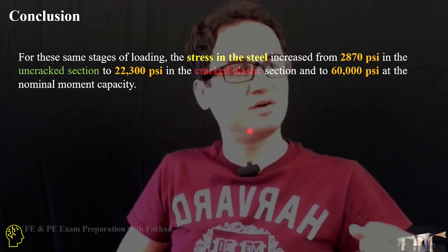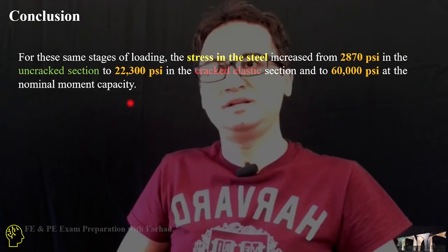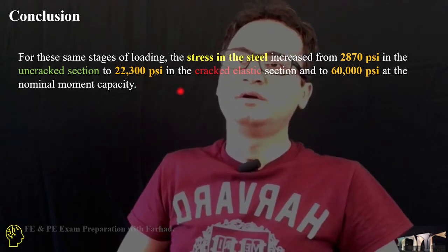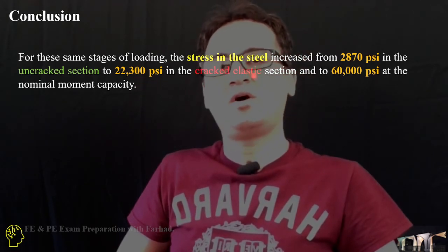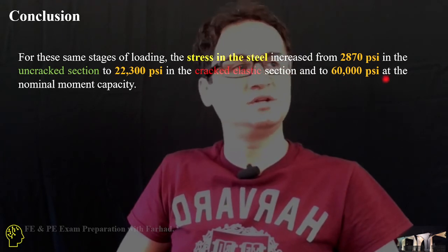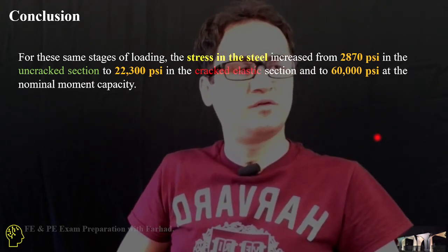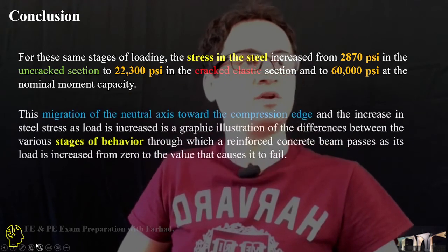Then when we are still in an elastic domain, but the section is already cracked, it moves to 22,300 psi, and all the way before failure of the section, it reaches the yield stress of steel, which is 60,000 psi for our problem at the nominal moment capacity.